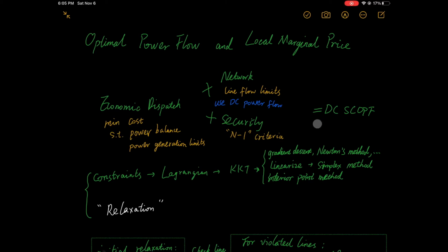And if we use AC power flow, problems will be nonlinear and non-convex. We usually combine our constraints into Lagrangian functions and use iterative methods to solve, for example, gradient methods and Newton's method. Newton's method is faster because second derivative information is used. But still, it is difficult to handle inequalities according to KKT conditions.